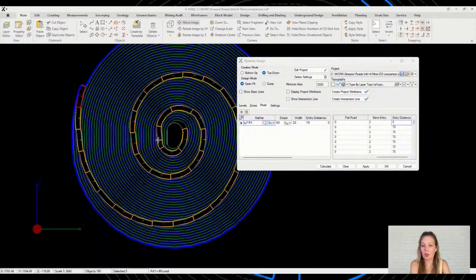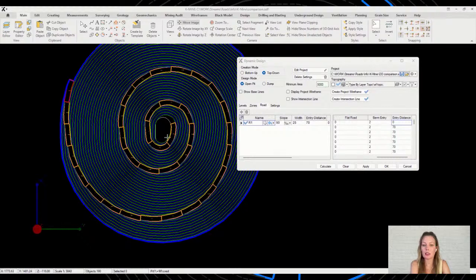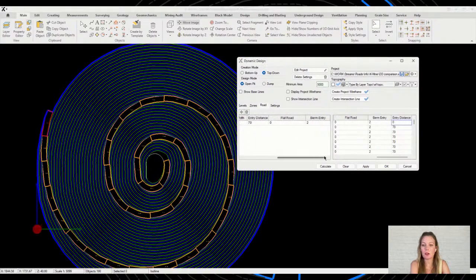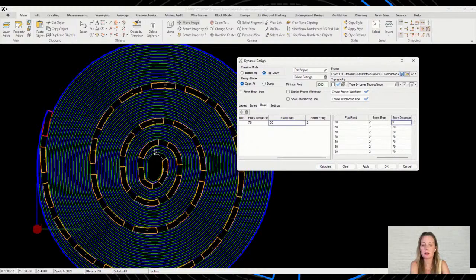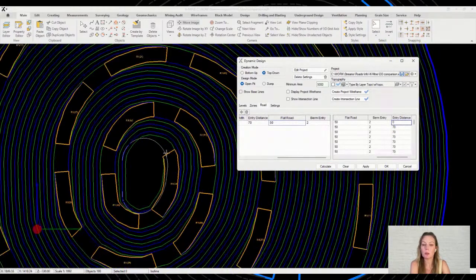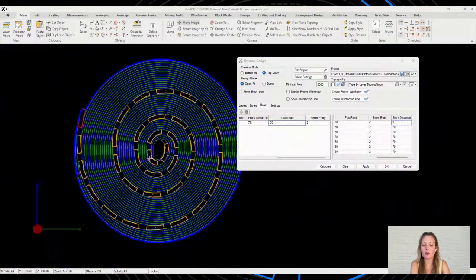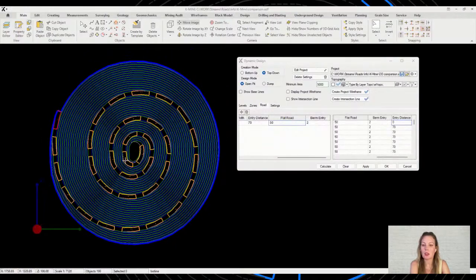This way, without horizontal inserts, we'll get a quarry identical to the quarry considered in option number 1, but we will add horizontal inserts. As a result, we will get a completely different quarry with different economic indicators. This example is simple and is used to clearly demonstrate the difference and impact of the presence of horizontal inserts as part of the road in a quarry.